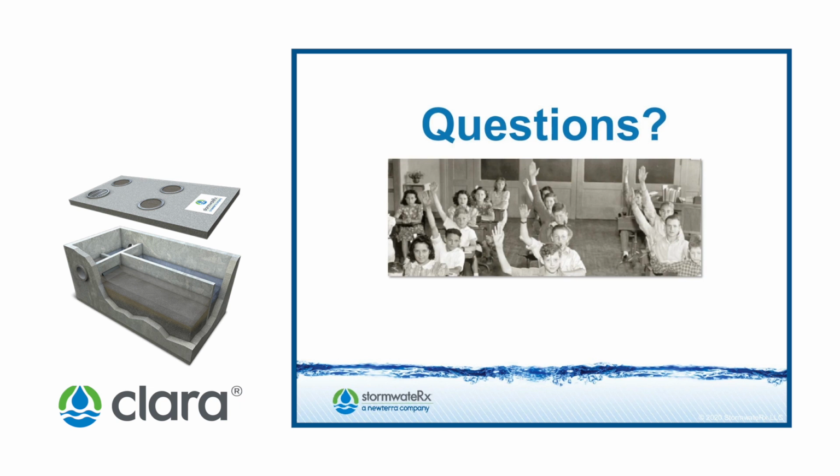And then Steve Fisher had another question. How was the sediment removed from the first chamber after settling? It's removed via a Vector truck. And we're talking about possibly a routine maintenance being the first 6 inches, Steve. That sediment would be vectored out to a depth of 6 inches, and then new media would be replaced. Hope that answers your question.